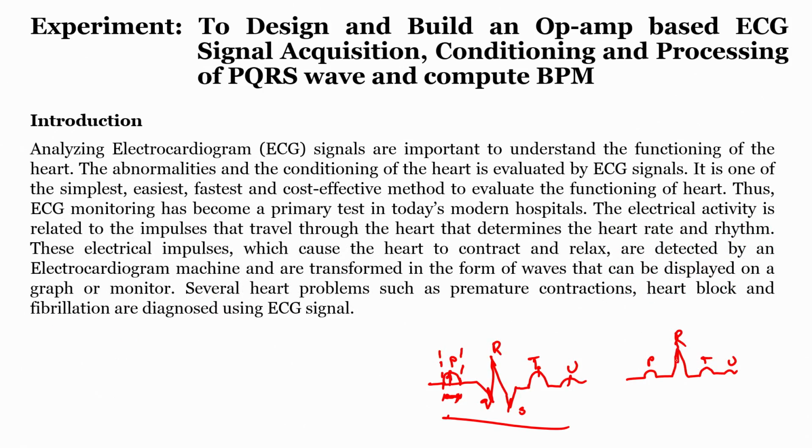So, if I want to calculate only the peak of R, I have to understand how I differentiate between a peak and a point, right. When I digitize the signal, we take different samples at different intervals. But how do you decide this particular value is a peak? In order to do that, I have to compare the value with the next subsequent value as well as the preceding value.